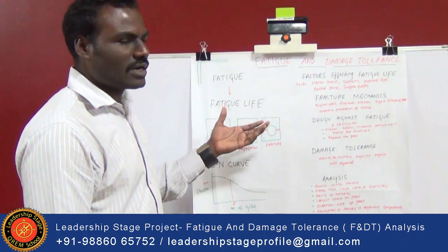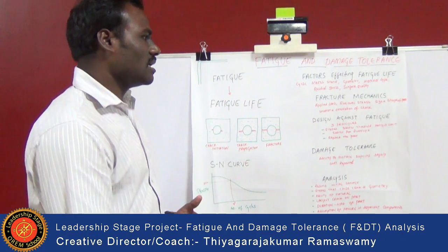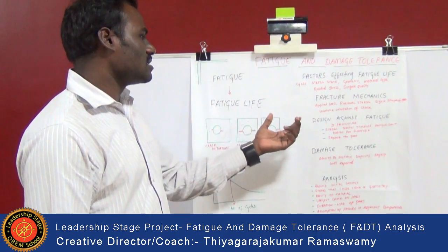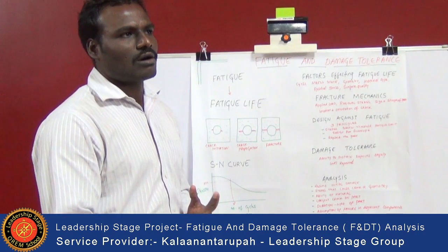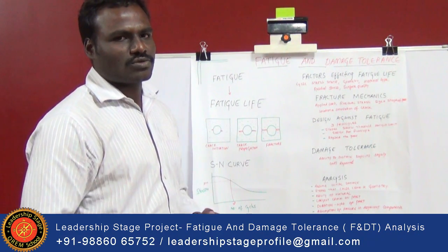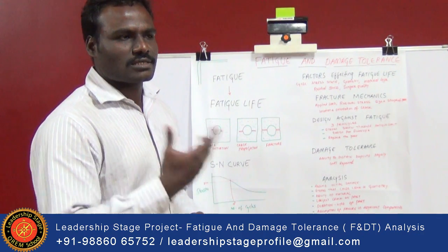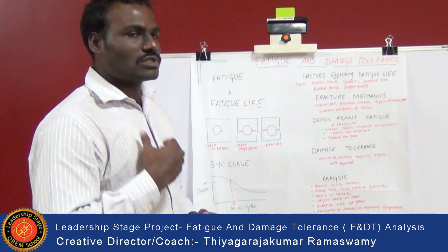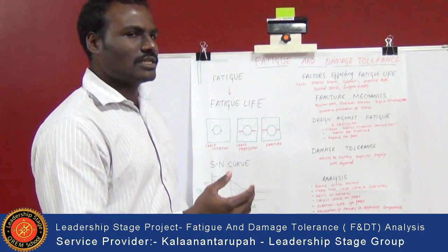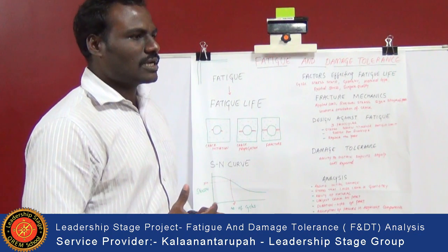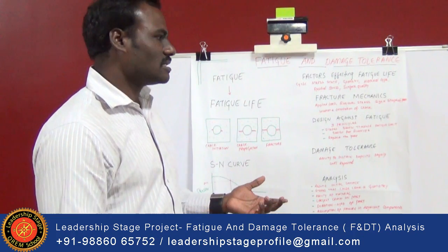Now we need to study the factors which affect the fatigue life. When a material or a component is subjected to cyclic loading and unloading with an excess amount of load or more stresses applied over a critical area or a complicated structure, it leads to a fracture, and the life of the component gets reduced.